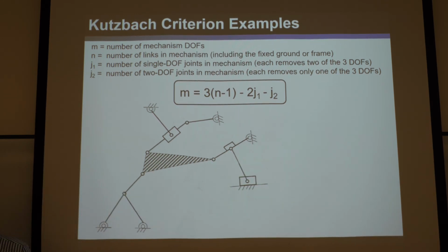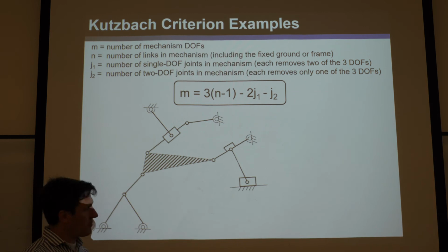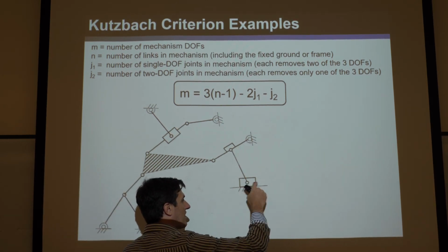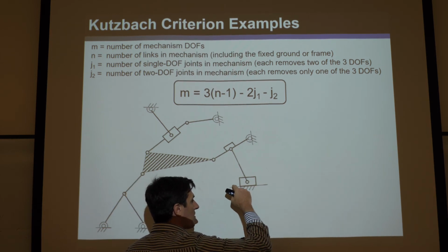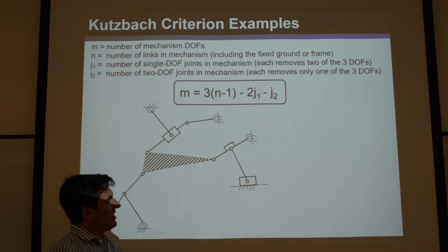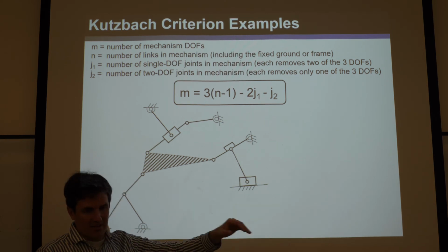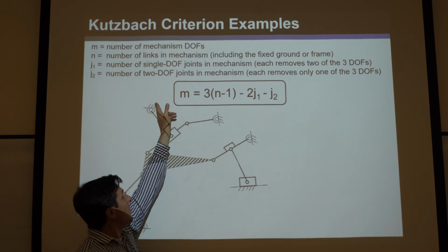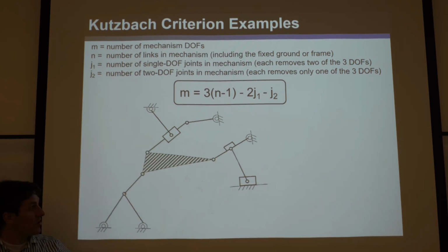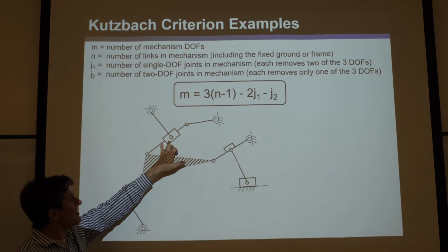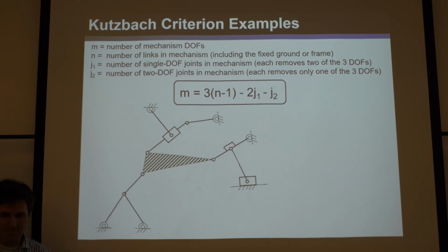So go back and look at that slide and just update in your mind: if you have any line that extends beyond the square, whether the hatches are directly below it or on the whole line or just on a part of the line, that whole line is grounded and the box can slide, okay? So this is a prism joint there. These guys are fixed, okay? And notice there's a bridge here, and here's a sliding prism joint. That's a link there. So with all that in mind, let's use Kutzbach and calculate the mobility.